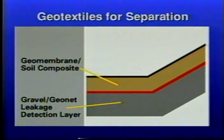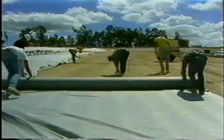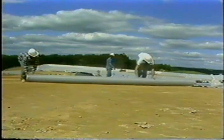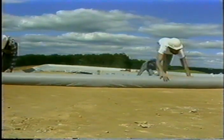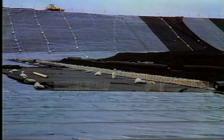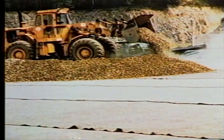Geotextiles are also used to separate layers of different solid material. For example, a geotextile can separate the compacted clay component of a primary composite liner from a layer of gravel or a geonet leakage detection layer. A non-woven geotextile placed below the geomembrane liner can protect it from being punctured by stones or roughness in the underlying leakage detection system. Non-woven geotextiles placed above the liner absorb impact or prevent abrasion from an overlying leachate collection or detection system, gravel, for instance.